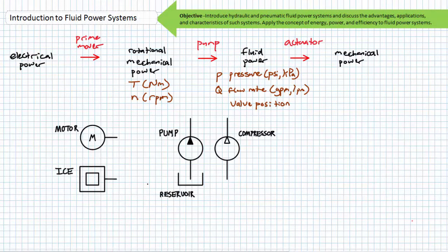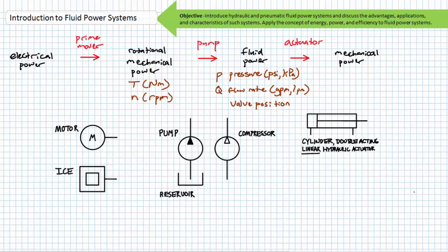Going back to our earlier diagram, this implies that the end result of a fluid power system is ordinarily the eventual conversion of fluid power into mechanical power. Actuators are the business end of a fluid power system where this conversion takes place. Linear fluid power actuators are known as cylinders. Cylinders extend and retract with a definable force, speed, and direction as dictated by the fluid power system pressure, flow rate, and valve position. Cylinders are ordinarily represented schematically as one would see them if bestowed X-ray vision and examined in profile. Pending construction variants, the schematic symbol may be modified accordingly.